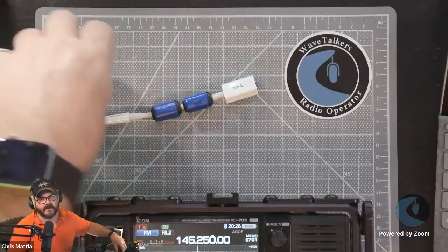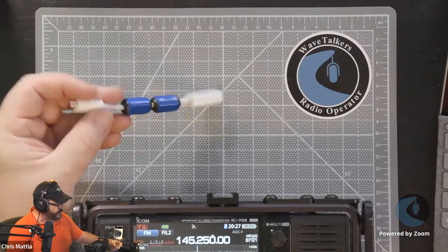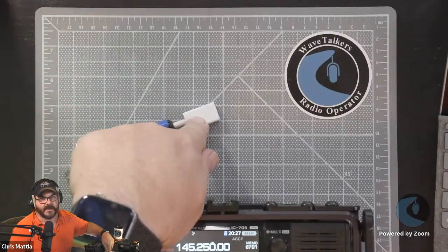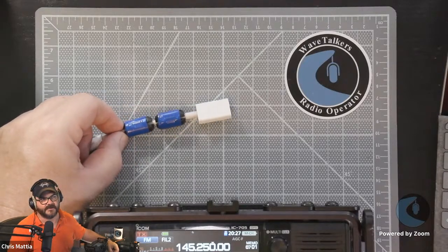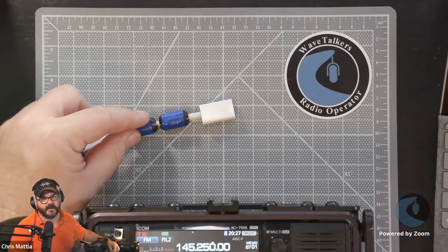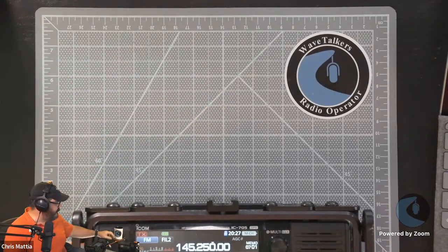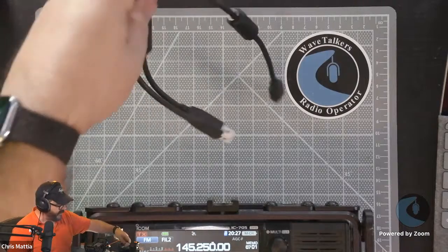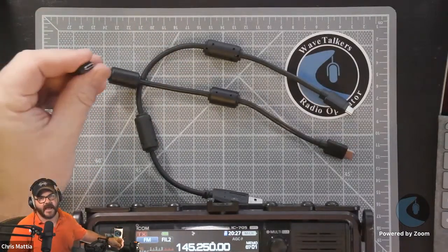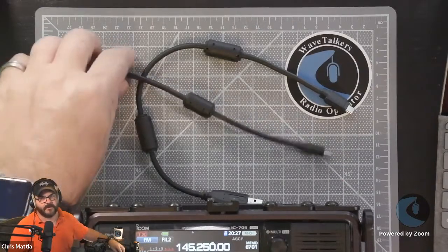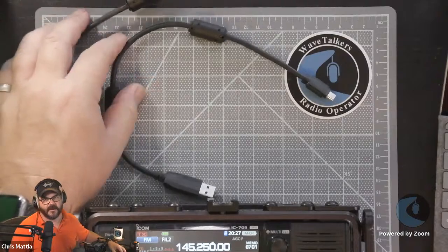So, for instance, I use these little adapters. Oftentimes, it's just got a USB-C on one end and then either a USB-A on the other, and load these things up with as many ferrites as you can fit on them, because more than likely what you're getting is a little RFI. The cables that I have found that work the absolute best are the cables that they sell through DigiRig. They have USB-C on both ends, or they've got USB-C and USB-A. You can pick these up.